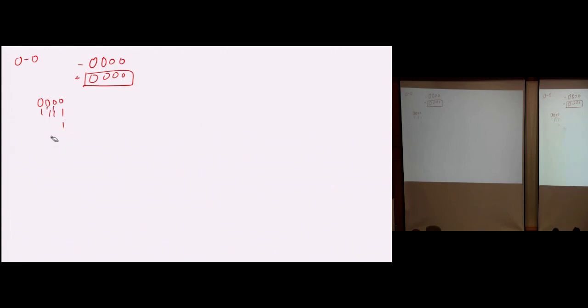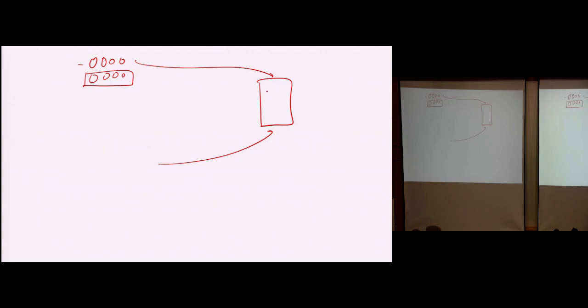So you're talking about the actual hardware, correct? So this one comes in here. Okay, so let's look at bit by bit. I have 0, subtract 0, correct? But since this is a subtract, this is plus 1. But this is 1's complement, so I need to have one more carry in. It is another 1 for the least significant bit.